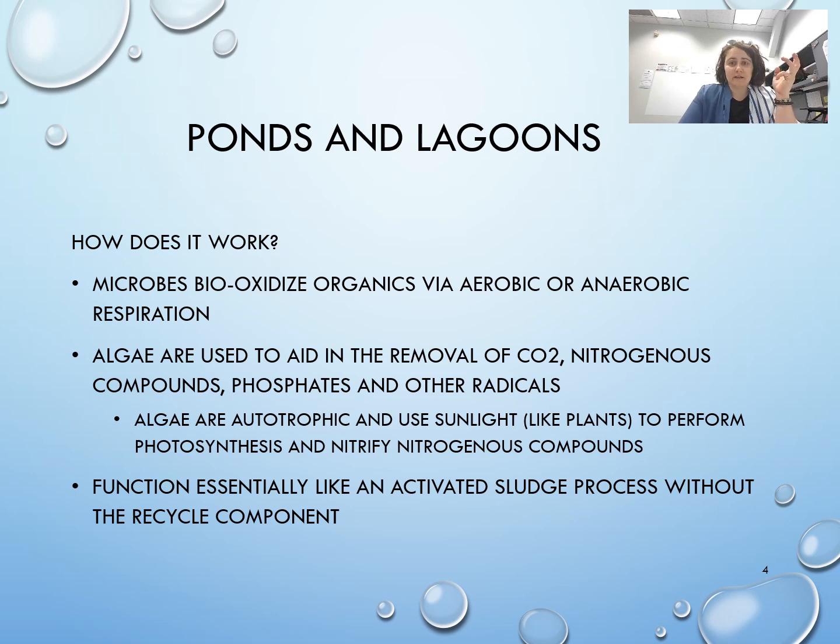So the idea is just like a lot of our aerobic digesters that we've talked about, we're using microbes to biooxidize organics using either aerobic or anaerobic respiration. It's normally a combination of the two. We normally don't have an anaerobic stabilization pond, we just have a stabilization pond. So it's always a combination of many different processes.